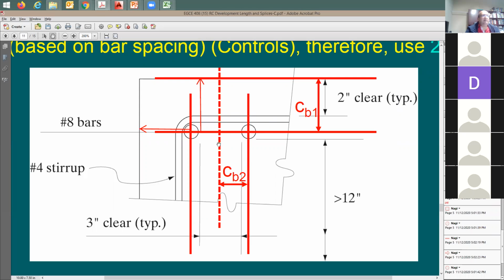You're going to be splitting these two zones for each rebar. Here's the first rebar, taking this concrete volume to develop the bar through it, and this is the other concrete volume that the other rebar goes through. So it's like tributary area. Exactly, very similar to it. You say how much confinement you have, or the amount of concrete surrounding this rebar.